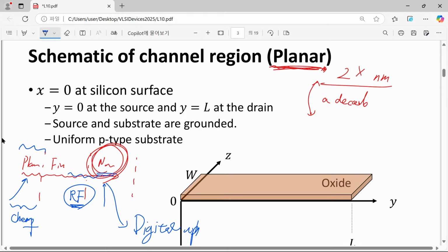When you make a digital circuit or digital system, certainly the state-of-the-art device shows much more benefit than the previous ones. However, RF is a combination of digital and analog. If the analog part is involved, then it is also related to certain capacitance inside the system. Parasitic capacitances are all very important. In that case, there is no guarantee that state-of-the-art technology shows much better performance than previous ones.